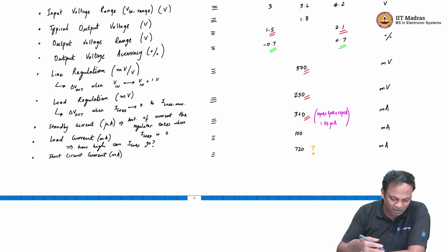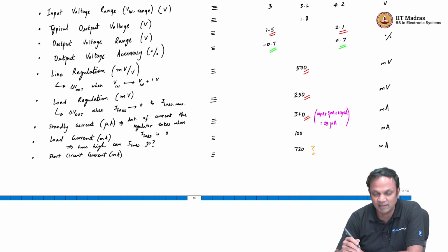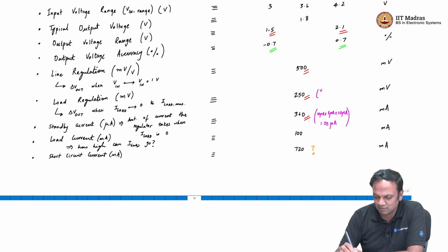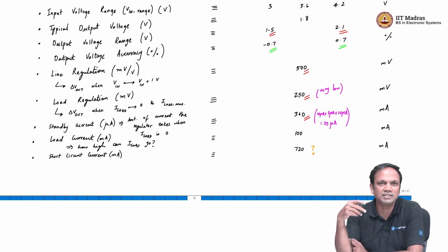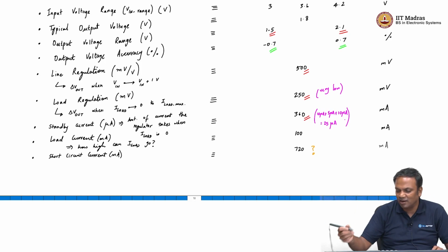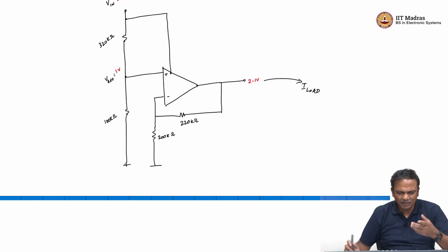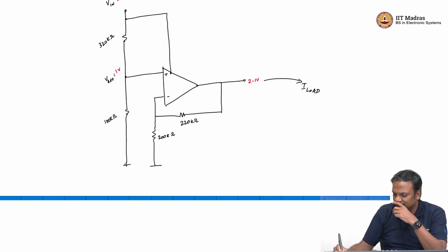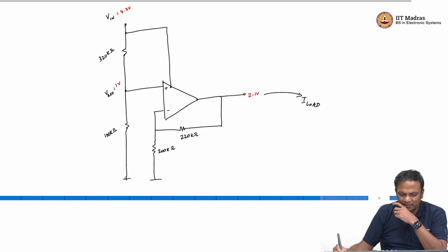So, we are not calculating the load regulation again. It depends on how the amplifier reacts to current, but what we know for sure is that this will also be very low, because an op amp has much better ability to provide current than a resistor does. So, we have now addressed the standby current as well as the load regulation. Now, let us come to the other thing. How does line regulation look? So, suppose I went with a circuit like this, how will the line regulation look?